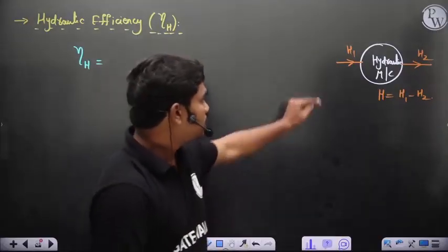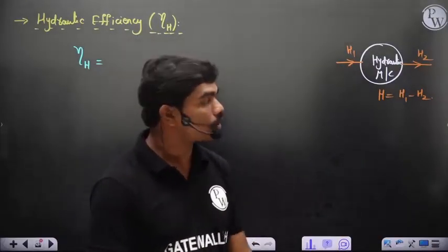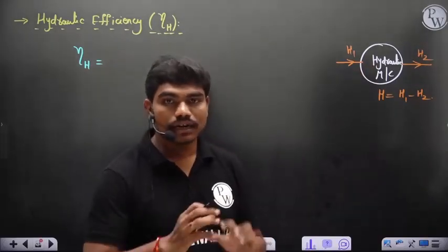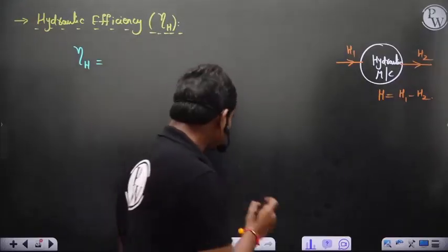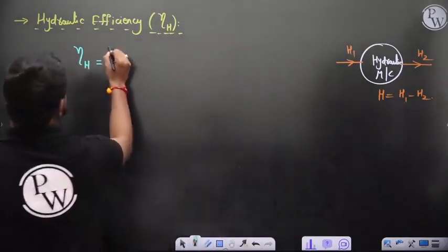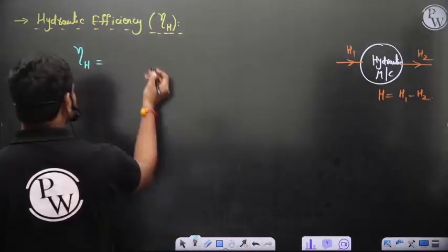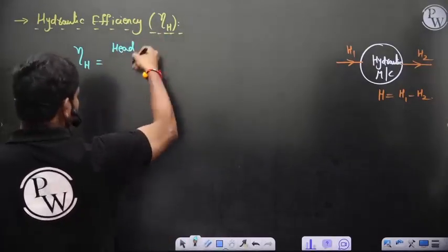Then this fluid, when it comes in interaction with this machine, delivers some energy, of course. So when this fluid is delivering some energy to this hydraulic machine, the machine's capability in taking energy from the fluid, this efficiency, is defined as head delivered, or energy delivered, basically you can write either. It depends because it's a ratio.